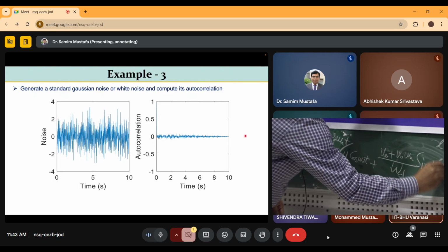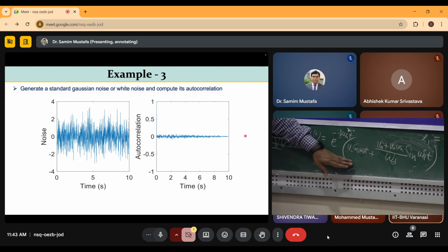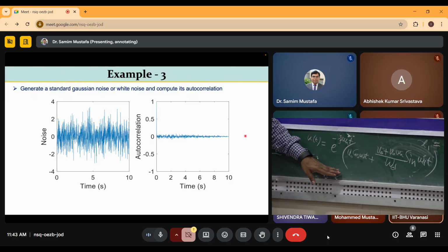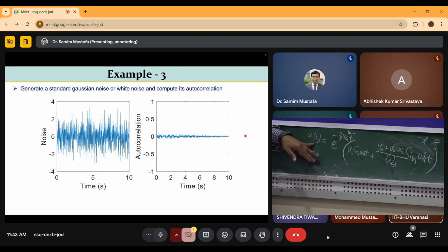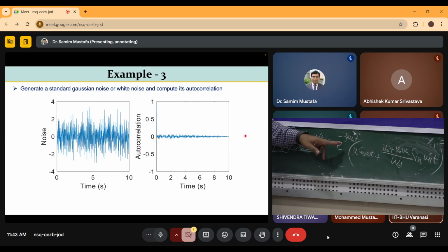Okay, this type of equation is there. If you solve it, you get the free vibration response with damping. So why not write the equation in MATLAB or Python? Just vary the time and specify xi, the damping, probably 5% damping. You can assume every structure has 2 to 10% damping. If I assume 5%, xi will be 0.05.